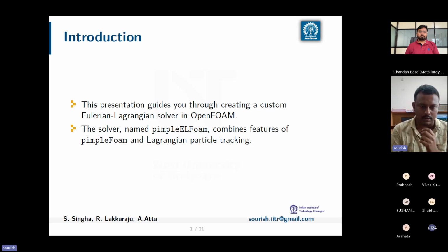So for this presentation, I'll discuss an Eulerian-Lagrangian solver. As you know, fluid we solve with an Eulerian method, and solids, if you have some particles, we solve in a Lagrangian method. Here we'll add these two and make a new Eulerian-Lagrangian solver. We'll take pimpleFoam, which is already available in the OpenFOAM standard dictionary, and also take source code from the Lagrangian particle tracking.